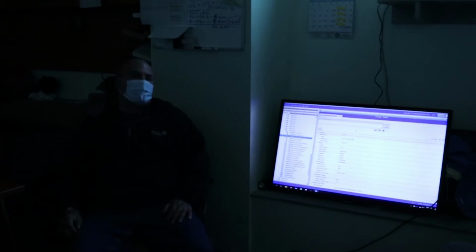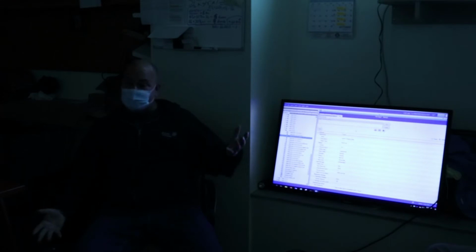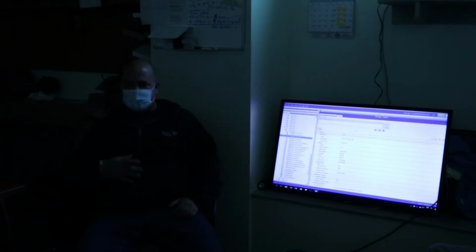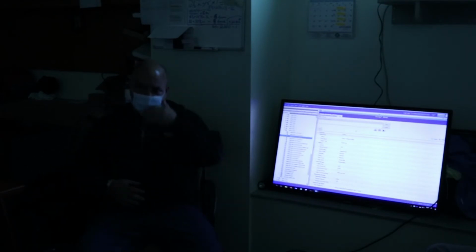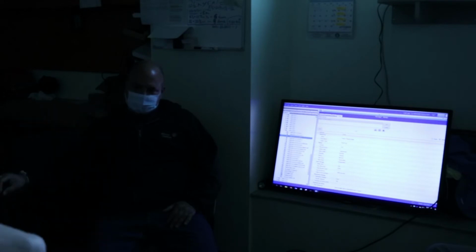What I've done is, if I'm really having a problem and I need to see a fast-acting trend, like I'm talking fast, like every 10 seconds, I'll just set it up for just a day, so I can see what's going on. So it doesn't stay in the system and bog it down, but it gives me the information that I'm looking for that day, maybe to see what was happening if I'm troubleshooting something.